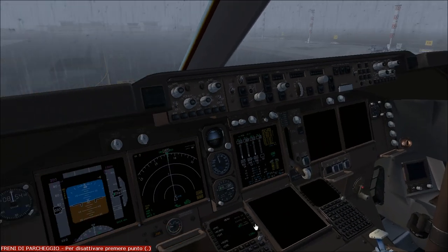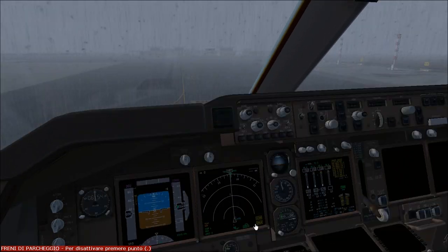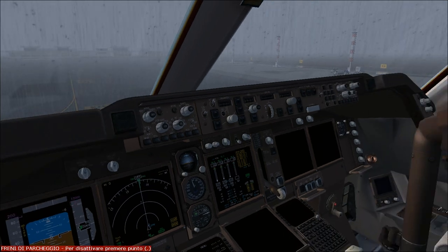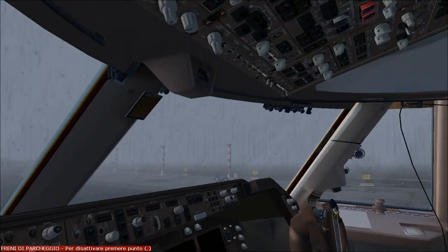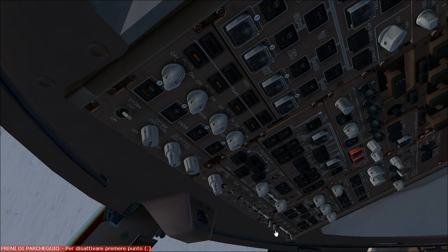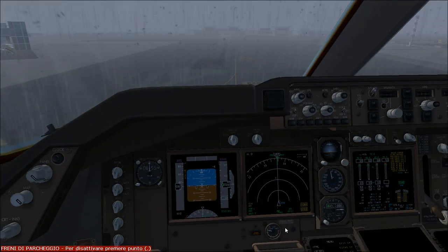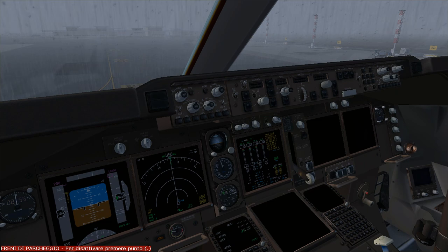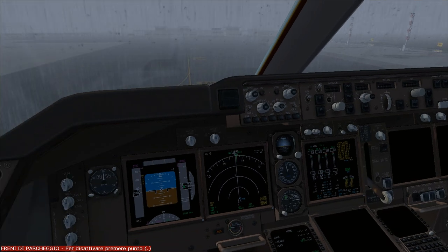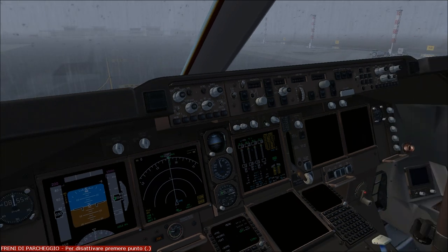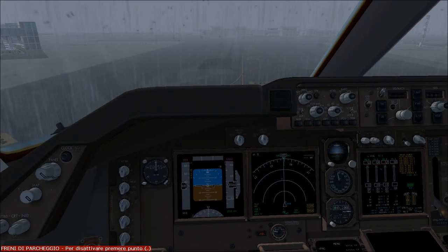The right side of the aircraft is off. This is just because we don't have the EPU turned on. Don't worry, this is fine. And we can now select the beacon lights to on. This is beacon lights off and left lights, keeping them on. This is actually shut down now. At this moment you should perform the normal shutdown checklist. It is pretty well explained in the Preflight Procedure. It's straightforward, nothing to explain, and so we can leave the tutorial here.